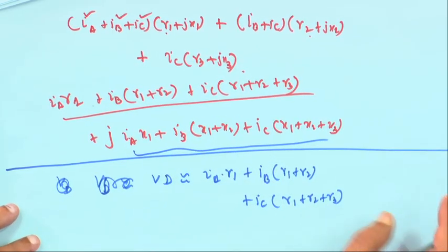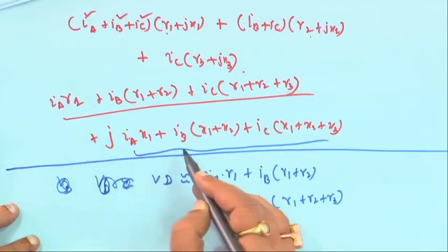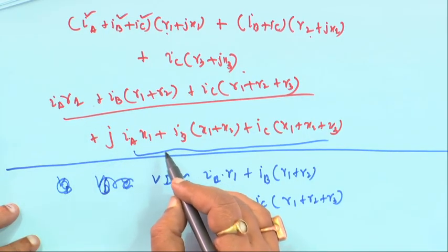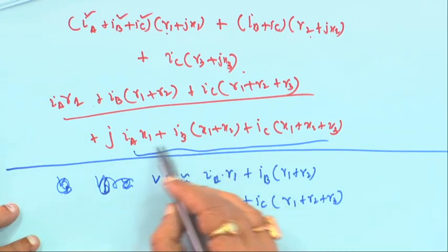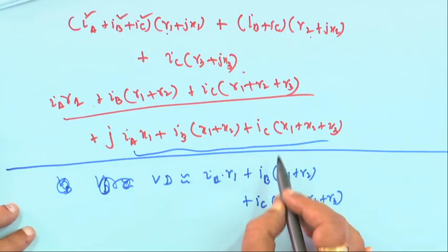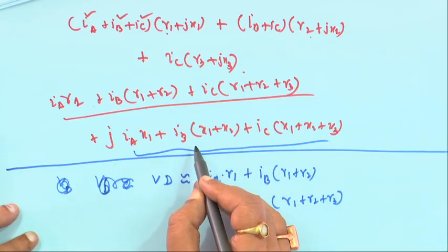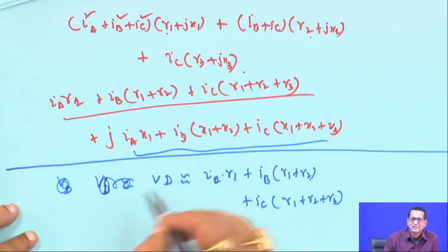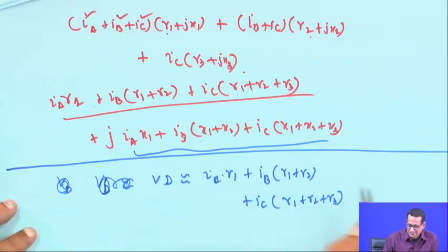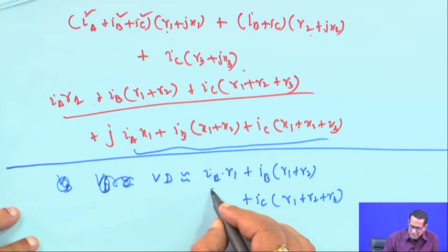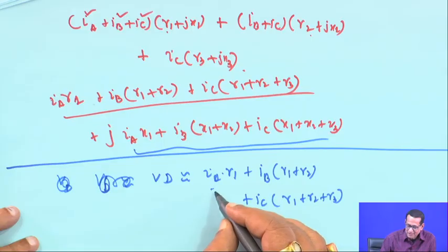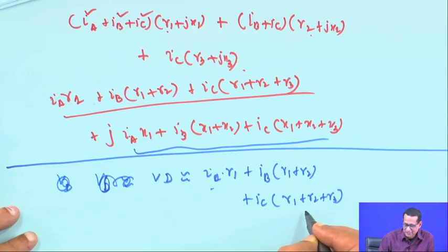Generally in a distribution system, the R values are higher, so the ratio of R by X is always greater than 1, right. So, that is why these values are much smaller and we did not consider them. The exact computation I will show you later. We have done it by calculating voltages V A, V B, V C, everything, but that is an approximate calculation, if you want to make an approximate voltage drop.